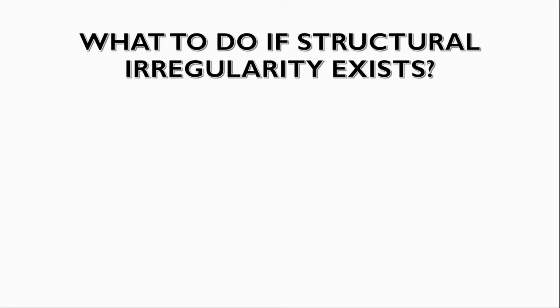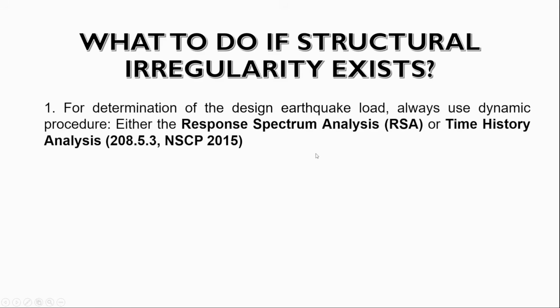So what shall we do if there is a structural irregularity? The first thing that we should do is always use the dynamic procedure. For design, we really need to have the demand. We cannot design our structure without the demand.